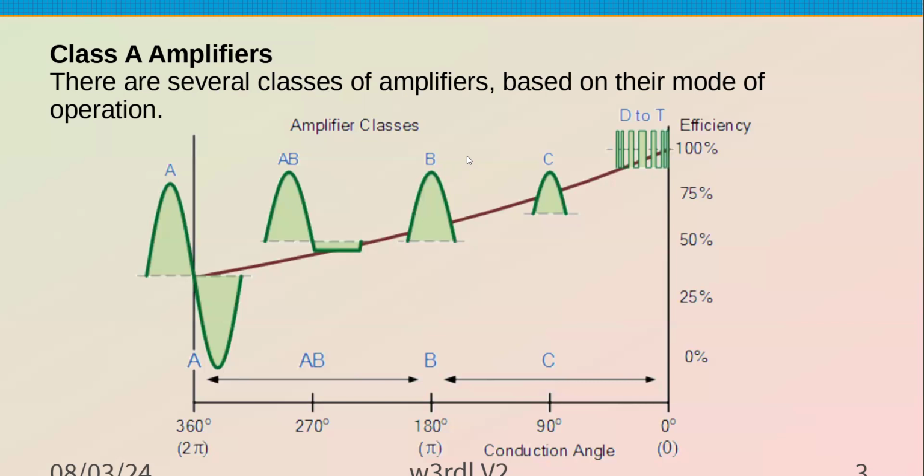Next comes class B, where you normally see those in what's called a push-pull configuration. One conductor handles half the wave. The device doesn't have to be biased on. It can be basically off and then go up to full conduction. So it improves the efficiency quite a bit.